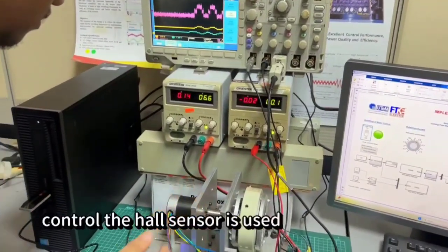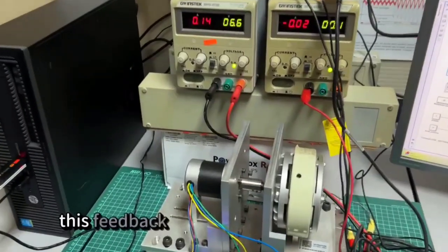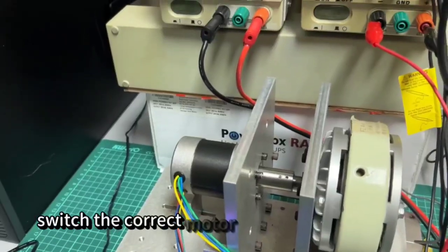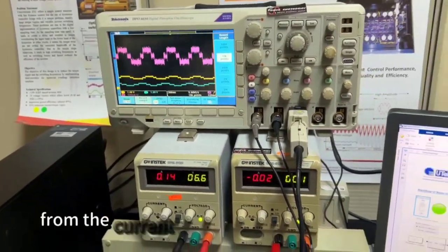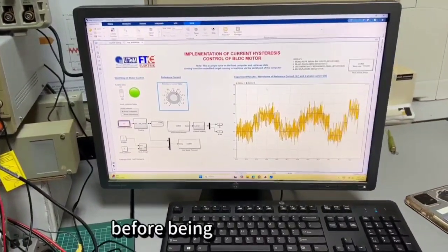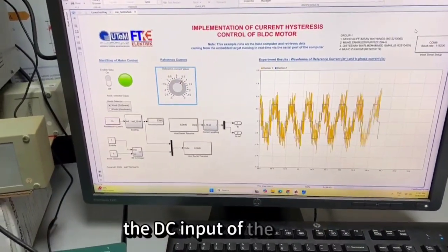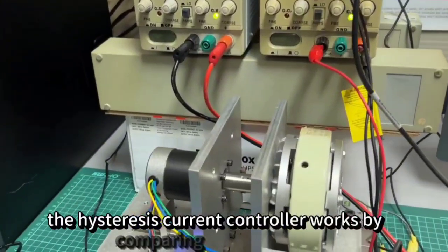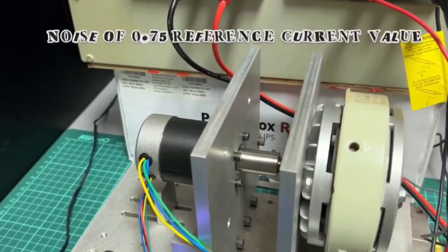The Hall sensor is used to detect the rotor position of the BLDC motor. This feedback is important because the inverter must switch the correct motor phase according to the rotor position. The output signal from the current sensor is passed through a signal conditioning circuit before being connected to the ADC input of the DSP. The hysteresis current controller works by comparing the measured phase current with the reference current.